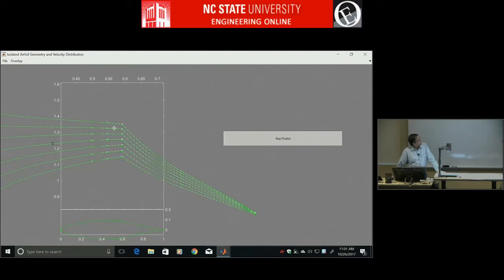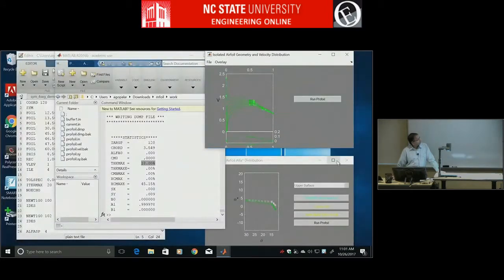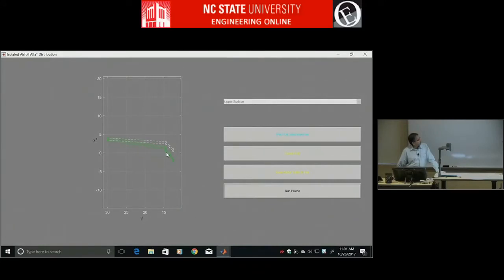Now let's go and see the velocity distribution. It's become a little more adverse, right? The earlier one is white. Now the green one is this. That means I have to make a really big change to make it even more nice and smooth. And you can keep going, right? So the way to think about in this plot is, if you move any point upward, it will make it more favorable. If you move it lower, downward, you're decreasing alpha star, you're making it more adverse. So we want these segments to be more adverse, so you pull them down.